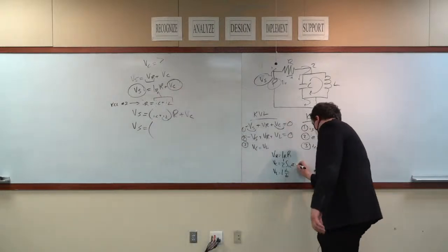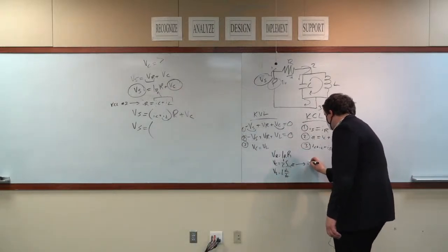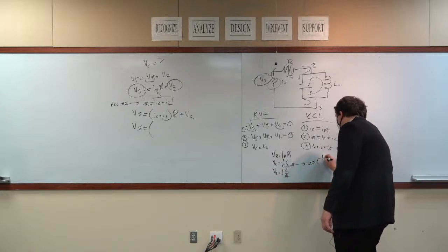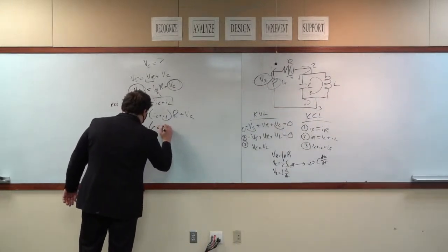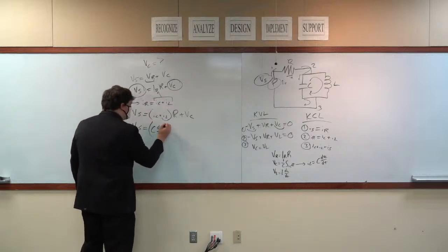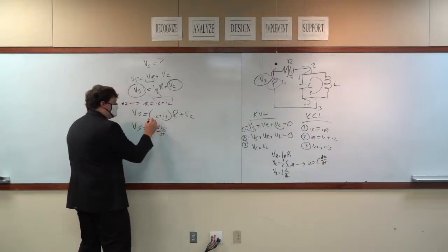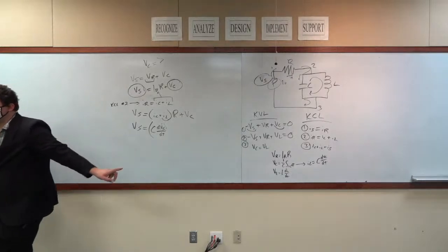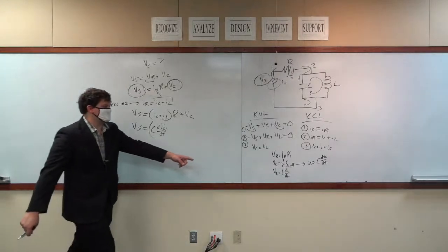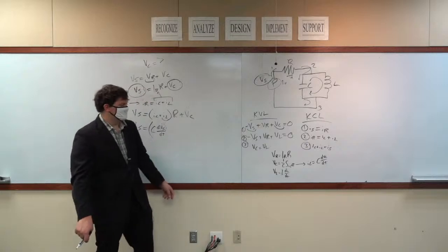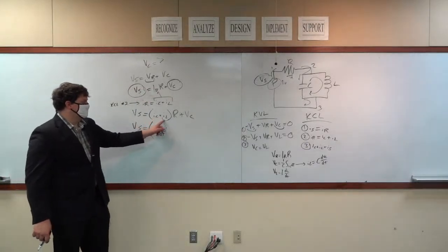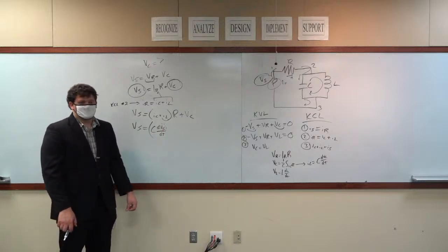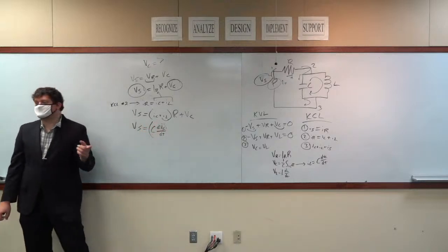If we're going to switch this around and solve for VC in terms of IC, IC is equal to C dVC dt. So this is equal to C dVC dt. Now the nice thing is we now have IC in terms of VC. We just use this relationship right here, that formula. But we still have this IL. Okay? IL has to depend on VC somehow.